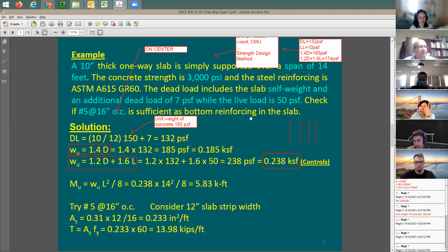So great. Now, how much is the moment capacity for this concrete slab? And when you look here at this moment demand, is this for a 1 foot strip? Think about it. If you look at the units for loads, it used to be here KSF, kip per square foot.